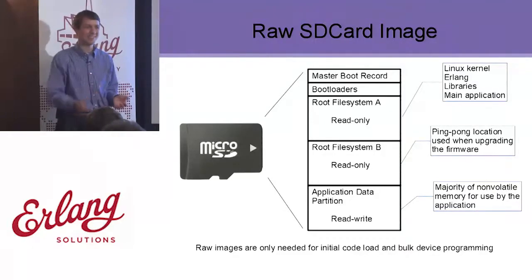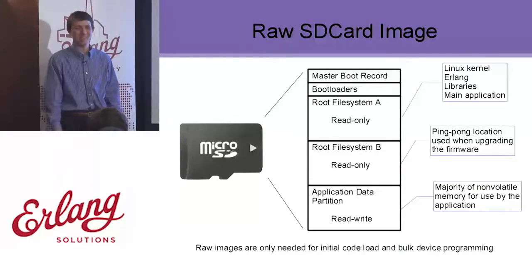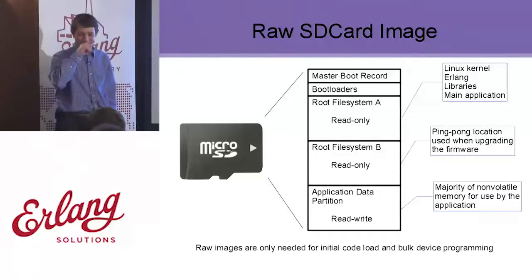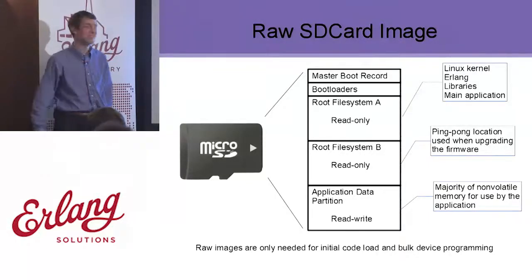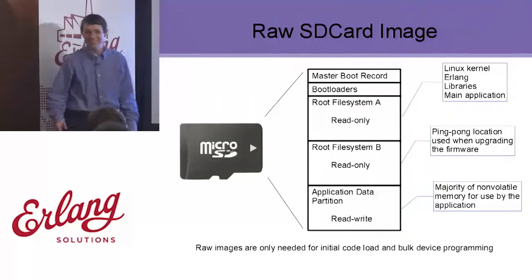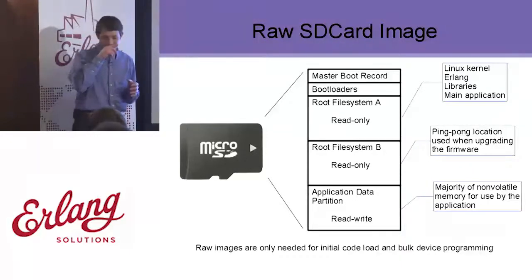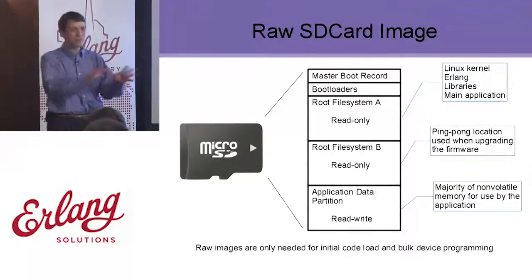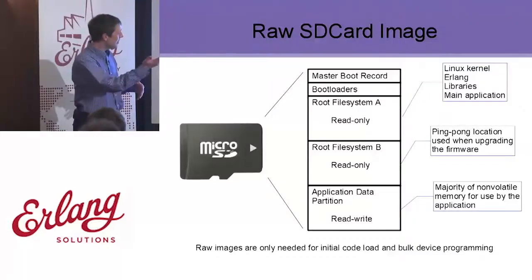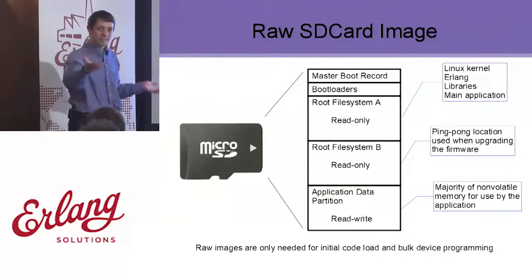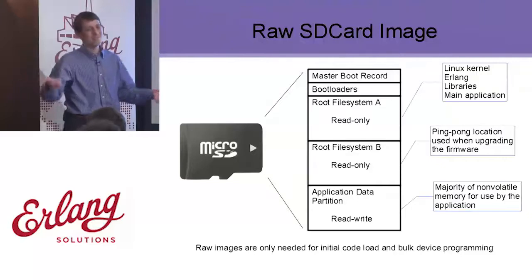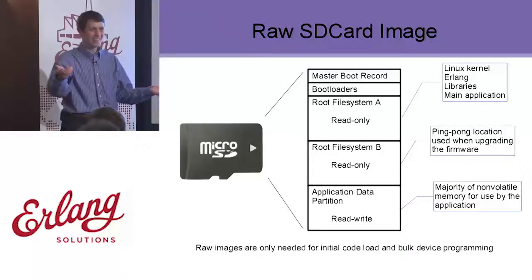I mean, if your file system gets corrupt on your hard disk, that's not good, but there are tools to fix it, and a lot of people put a lot of effort into giving desktop users help with this. But embedded is not that way. So I keep my file systems read-only to minimize the possibility of messing them up. That makes development a little bit trickier, but you can work around it pretty easily. So when these things get burnt, you just boot up with a file system that's read-only. Someone pulls the power, fine. Nothing lost. It's read-only.